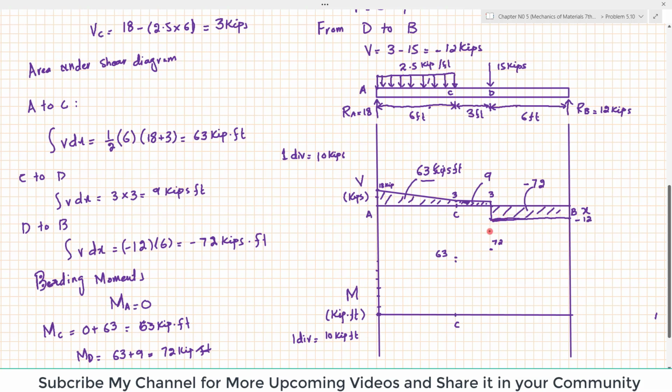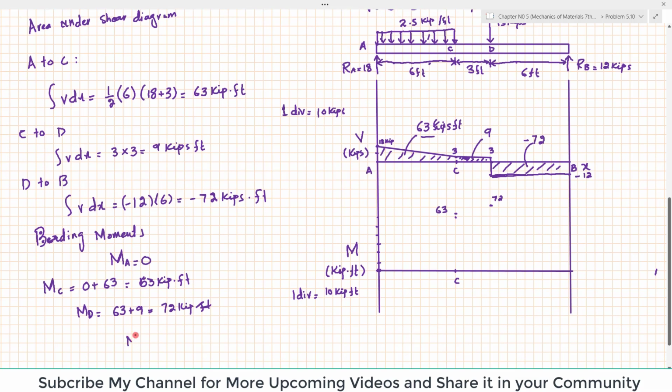And remaining is the moment at point B. So moment at point B is equal to moment at point D plus this moment, which is minus 72. So moment at point D is 72, and the area under the shear force diagram from D to B is minus 72. So it will be equal to 0. So this will be the moment at point B, which is equal to 0.